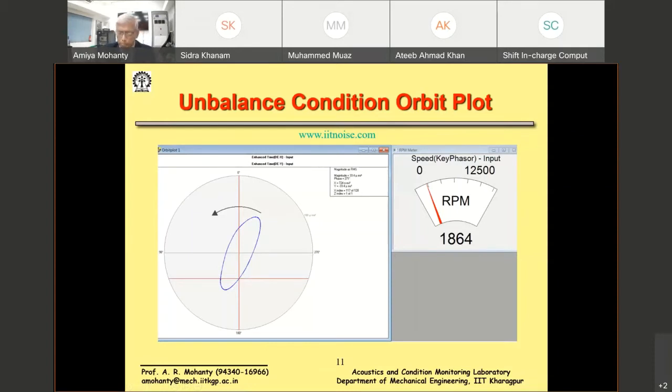If you go to any turbine manufacturer, be it BHEL, etc., in their test plants or test rooms, you will see they put eddy current proximity probes at different stages of the turbine, and then they monitor the orbit. This is very easy for the technician to just look at the plot and see if the orbit has gone bigger in diameter, or the ellipse has expanded.